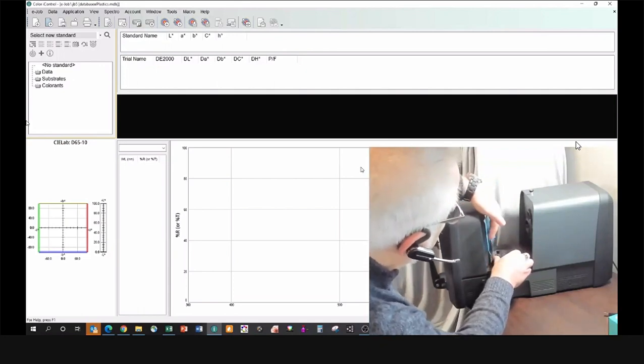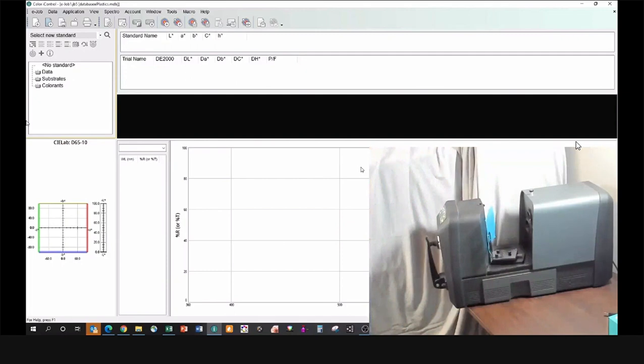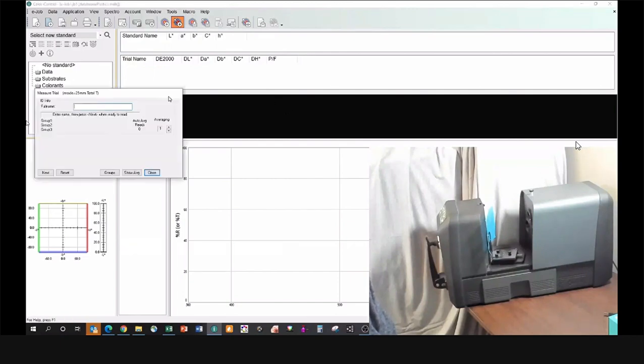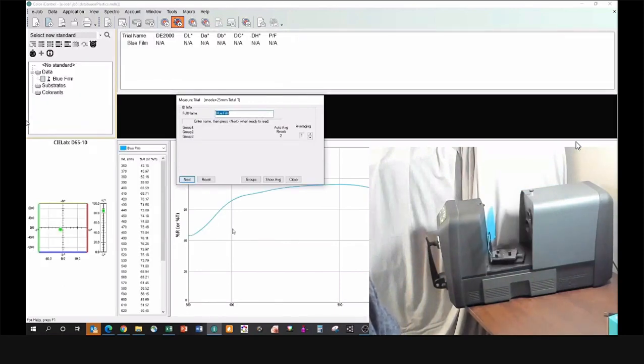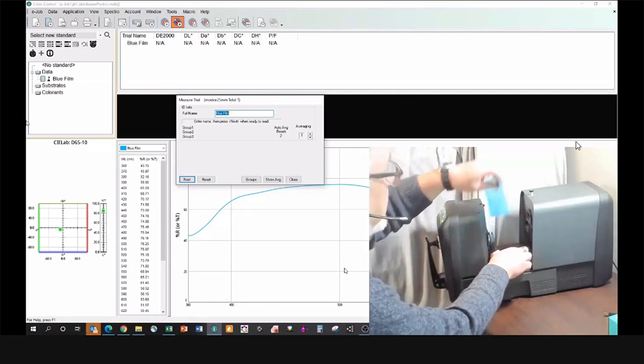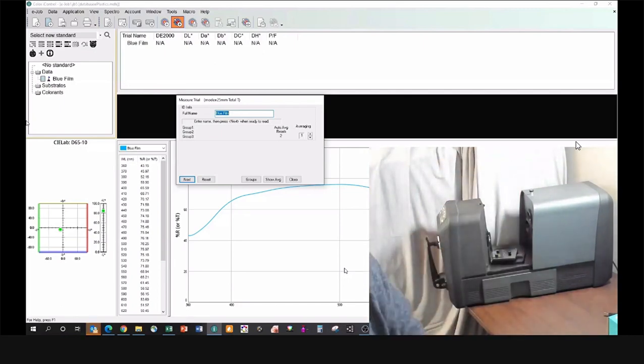What do you think? Will he measure total or direct measurement? So for this type of plastic, it's not transparent. It's a bit hazy or a bit opaque. So he will use the total transmission measurement. Depending on the sample transparency, if you have a sample that is not 100% transparent, then you have to do total transmission. Direct transmission method is normally used for clear measurement or clear film or clear samples.